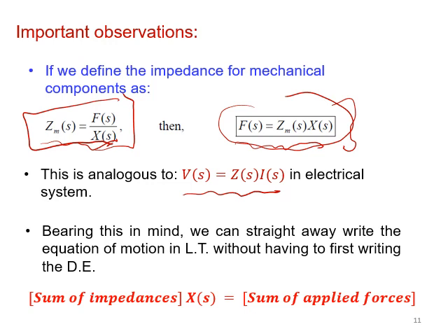So when you compare this with the equation developed earlier, you will find it's nothing but the sum of impedances times X(s) is equal to the sum of the applied forces. So without going through the steps mentioned earlier, we can directly develop the equation using this idea.